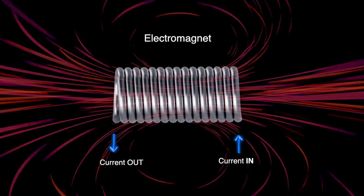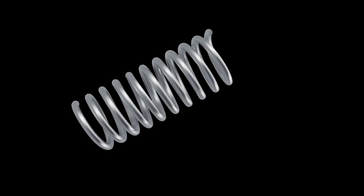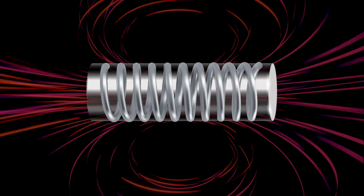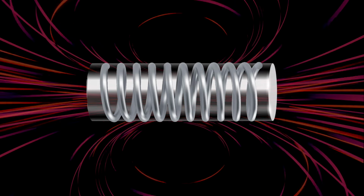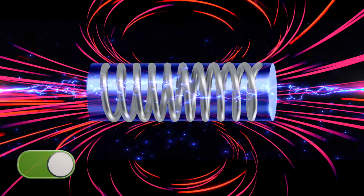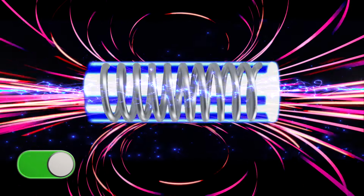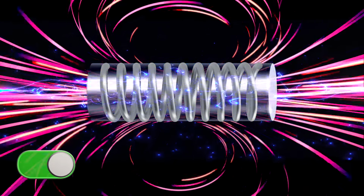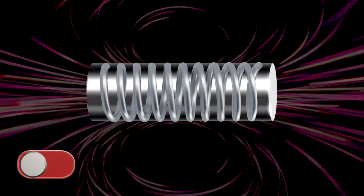Alternatively, reducing the length of the solenoid while maintaining the same number of turns can also strengthen the magnetic field, as electromagnets with densely packed coils are the most effective. Finally, inserting an iron core into the solenoid can significantly amplify its strength. Iron, being a soft magnetic material, becomes magnetized when the solenoid is active, greatly enhancing the magnetic field. However, it is important to note that the iron core will lose its magnetism as soon as the current is switched off.